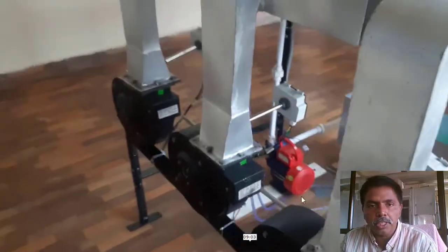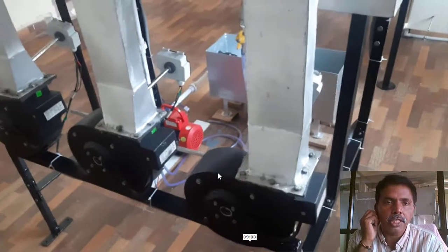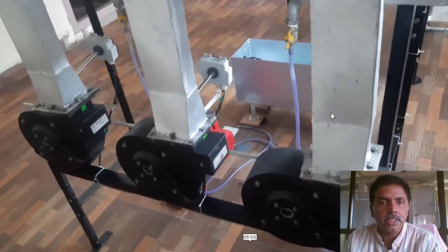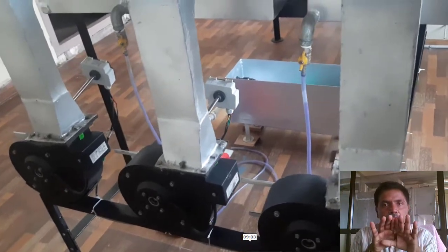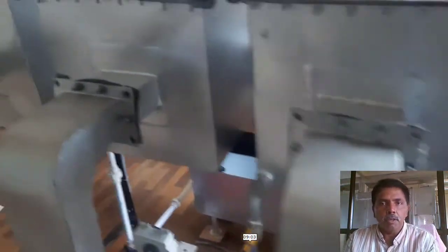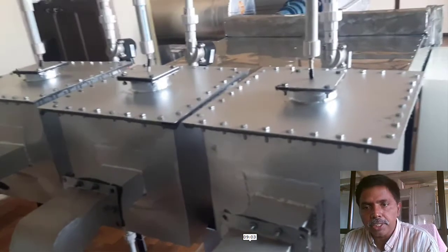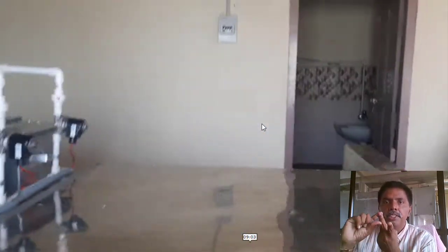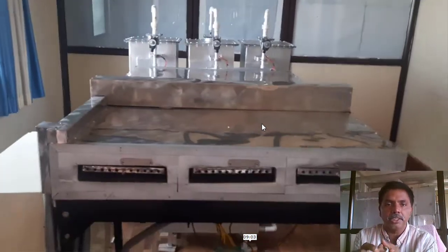According to the opening of the dampers, we can achieve different mass flow rates of the air. This is the flow rate measuring sensor. So there are three separate facilities with different temperatures and different relative humidity. Here we placed heater coils, connected above the insulation. So three heater coils separately, for three different inlet temperatures and different relative humidity input conditions.